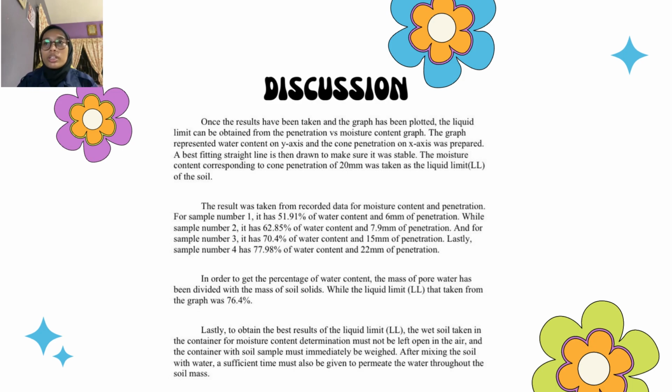Lastly, to obtain the best result for the liquid limit, the weighed soil taken in the container for moisture content determination must not be left open in the air, and the container with the soil sample must immediately be wiped.